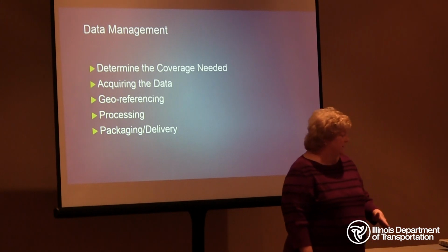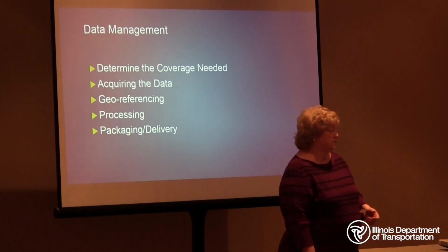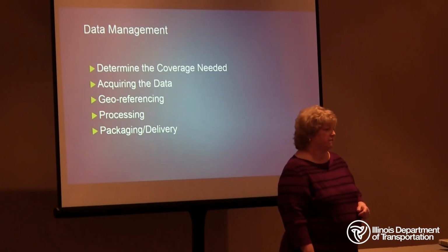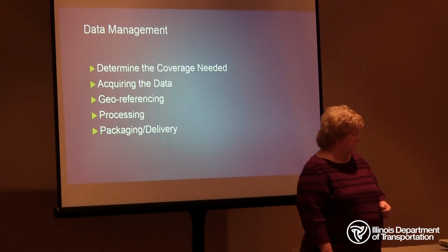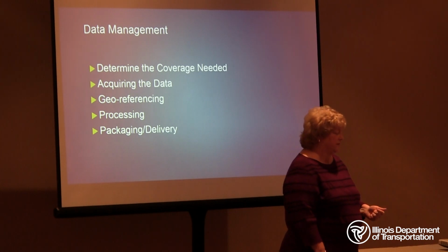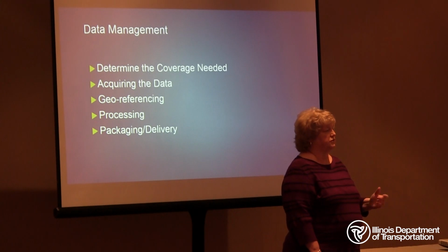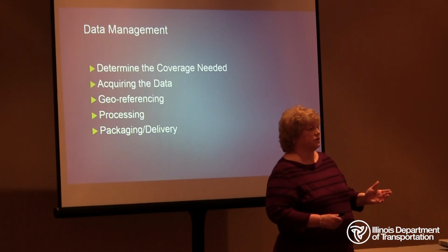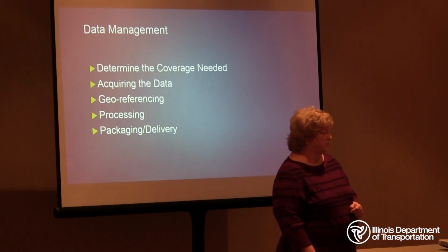When you're processing and analyzing the data, you're using software such as TopoDoc that Pete showed to manage the data, access the quality, and extract the information necessary for design, engineering, and construction operations. When you're packaging and delivering the data, you want to complete the changes to the data and package it up so that you can give it to the user to be used for design projects. You may want to tile the data, and what that is, cut it down into smaller chunks to be able to transport it, and that way it's easily accessed by the user.